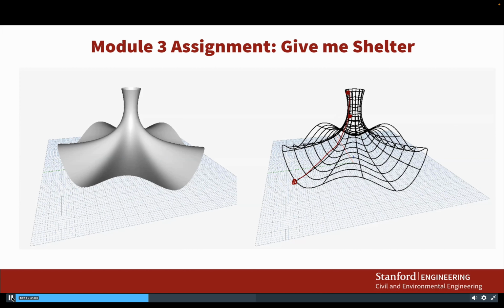However, for the transverse curves, you would need a different approach because they have more points to get the shape. So what you could do is choose a 2-point adaptive component and straighten out all of these segments, which also will help you when you get to the panelize part.